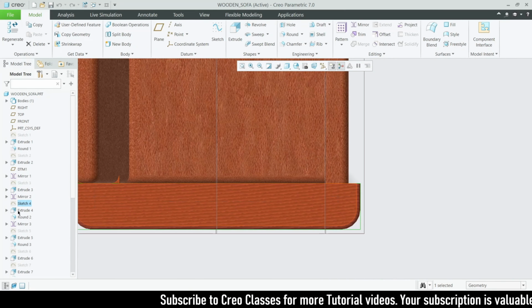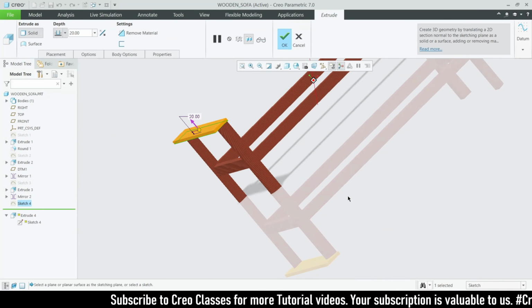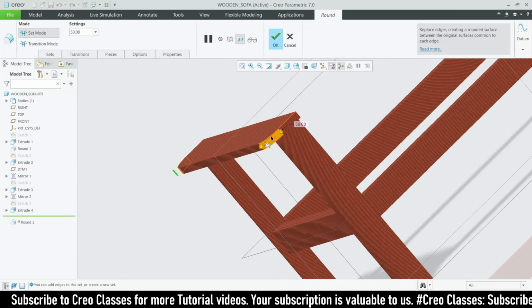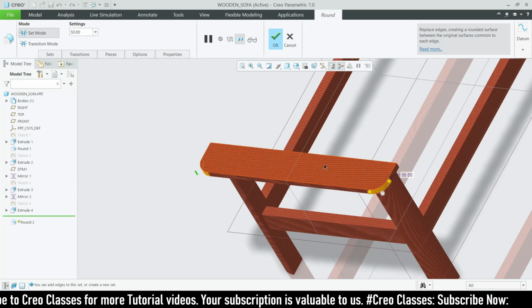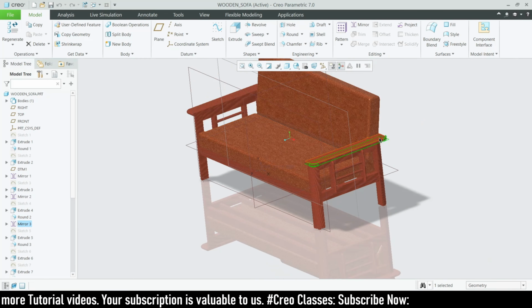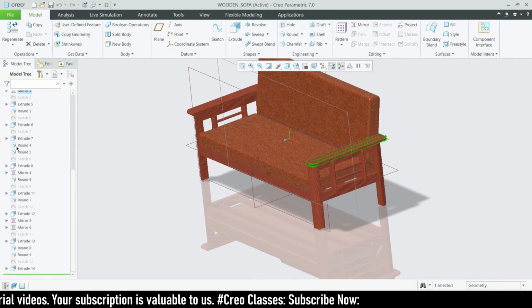After that, let's extrude that. The extrude height is 20 from the face. Then round both edges, which will be 50, and then we have to mirror everything on the other side. Good, right?